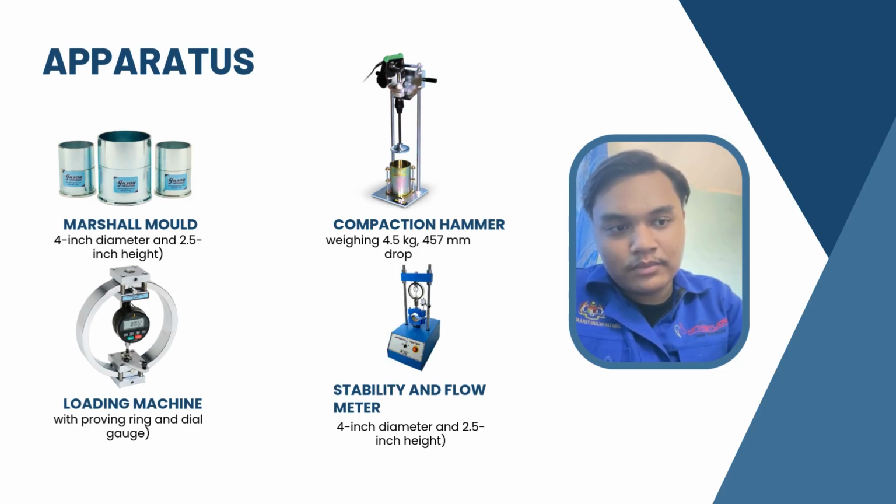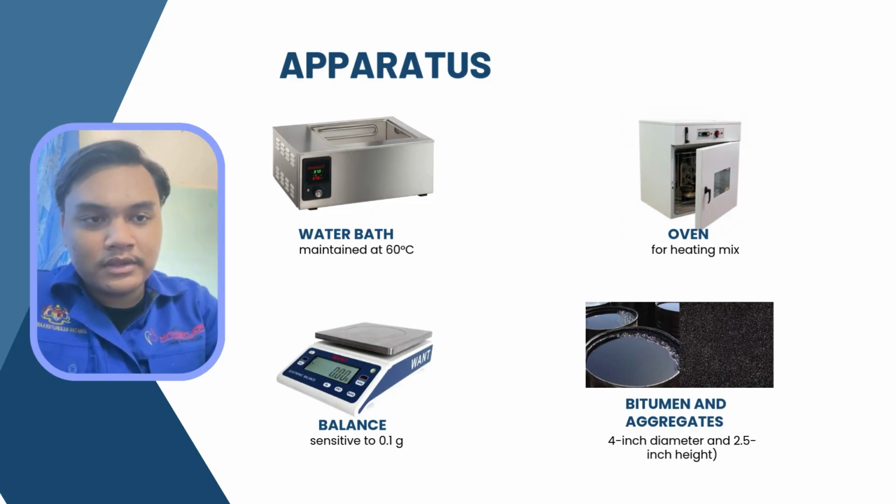Last one for apparatus is water bath, maintained at 60 Celsius. Oven for heating mix, balance sensitivity to 0.1 gram. Bitumen and aggregate.